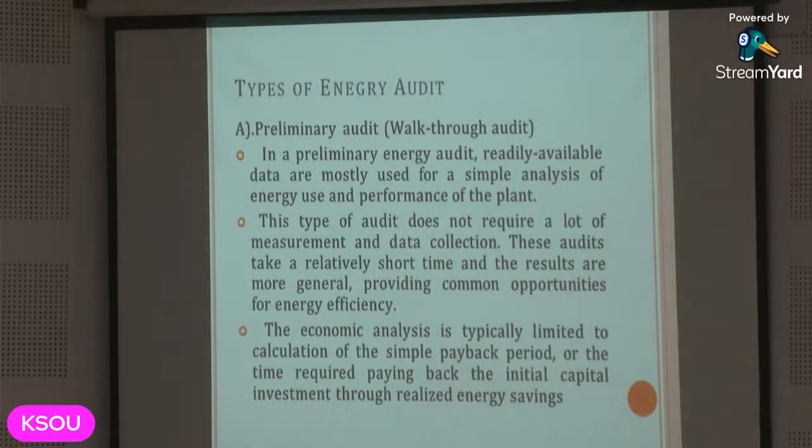How many lights are there? What is the lux level required? If you have more lux at the back, there is no purpose, so we can switch off the backside row. So that is a simple audit. Just walk through, identify the opportunities for improvement, and implement them.